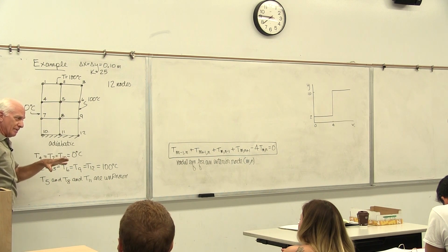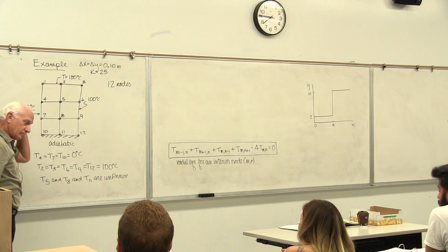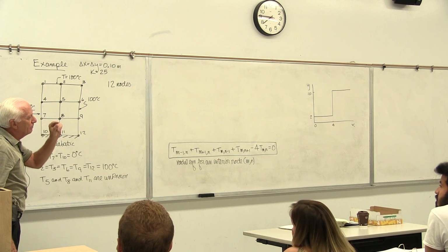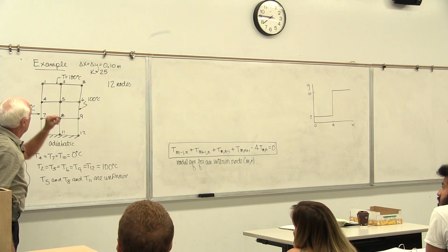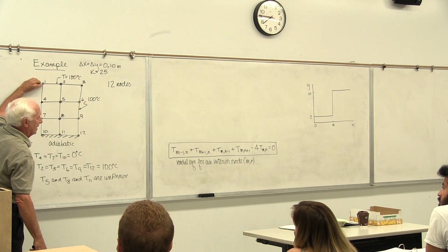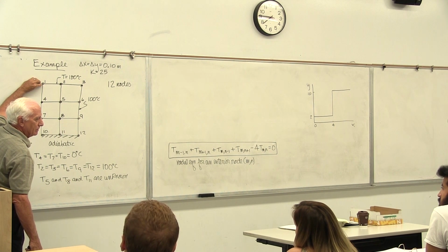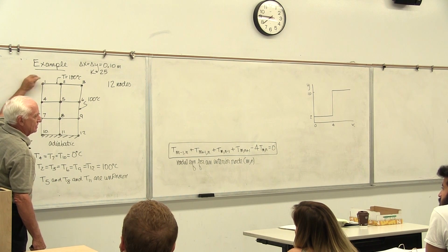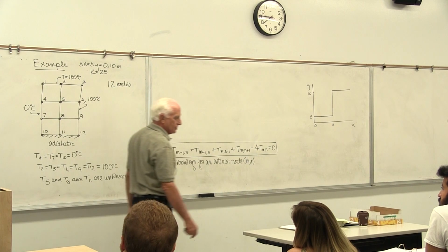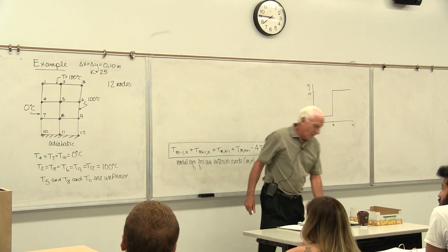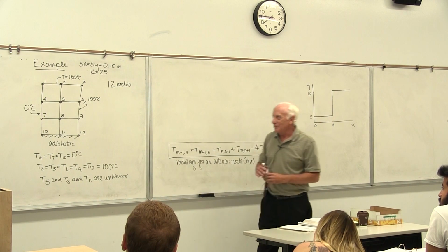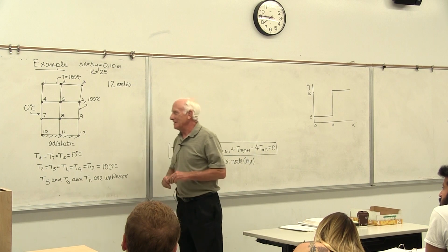So what do you do to get around that experimentally in a lab? You take a little square piece of insulation for the electrical problem and put it up there so they can't touch each other. That's the point. What would you do here? Put a little thermal insulator right there so they can't touch each other. The 100 degrees won't touch the 0 degrees. Otherwise, you've got a thermal short circuit. Okay, so now that's T1. Good question. I'm glad you asked it.